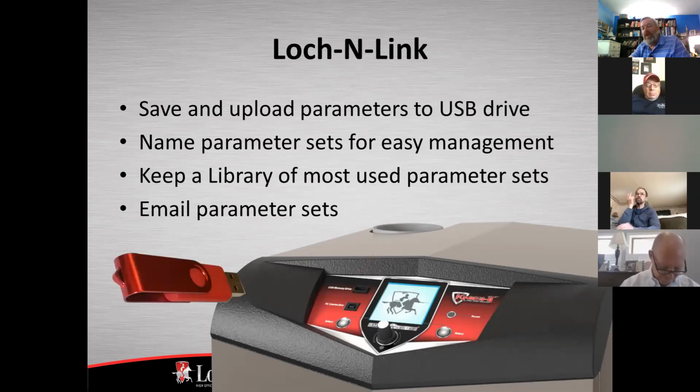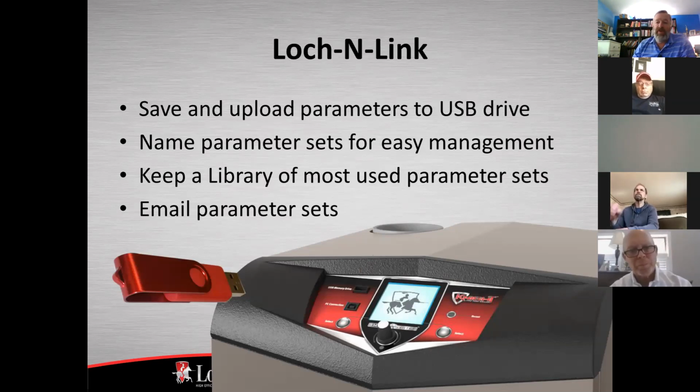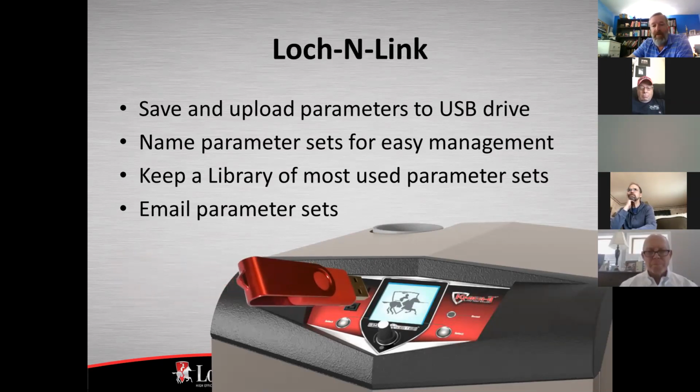Now this feature is on the 3rd generation display. So this one with the big red overlay around it is the one that you can use that. Now a couple of cool things you could do with that. One is if you talk to your distributor, your Lochinvar distributor, or your FIA salesman, you can get a pre-programmed thumb drive to use. If you want to program your boilers and then upload those parameters to a thumb drive to use on other ones, you can do that as well. It's kind of a slick little tool that's there. Okay, just plug it in and go.